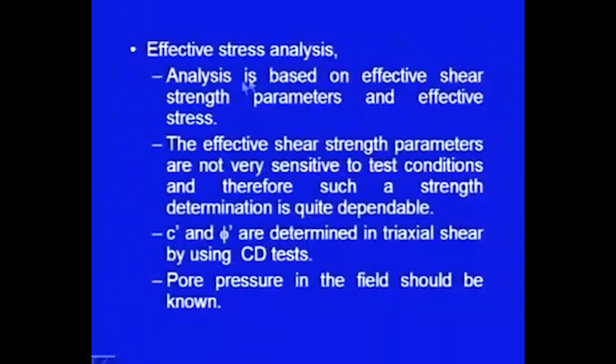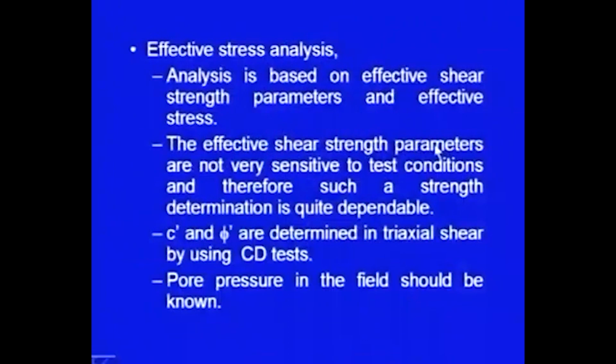In case of effective stress analysis, the analysis is based on effective stresses and effective shear strength parameters. We consider c dash and phi dash, not c and phi, and also we take sigma dash. The effective shear strength parameters are not very sensitive to test conditions, and therefore, such a strength determination is quite dependable.